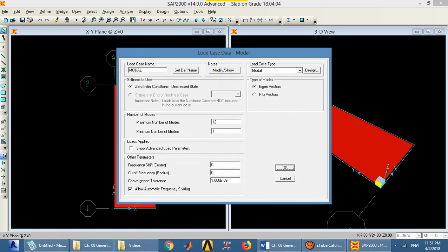Then I go to modal analysis. Here in modal analysis, I will solve the resulting characteristic equation to determine the natural frequencies and mode shapes. This procedure is similar to determine the root of characteristic equation, but here we have a mass matrix instead of mass in single degree of freedom.